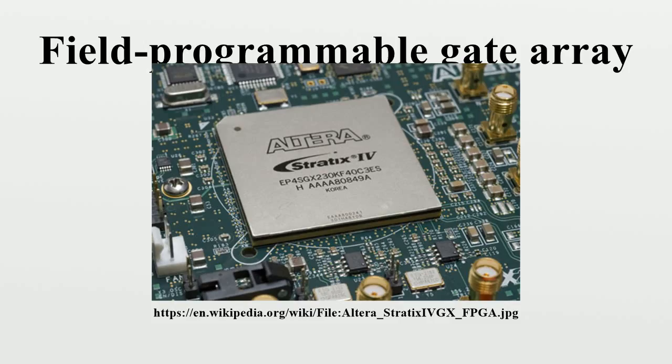A few mixed-signal FPGAs have integrated peripheral analog-to-digital converters and digital-to-analog converters with analog signal conditioning blocks, allowing them to operate as a system on a chip. Such devices blur the line between an FPGA, which carries digital ones and zeros on its internal programmable interconnect fabric, and a field-programmable analog array, which carries analog values on its internal programmable interconnect fabric.